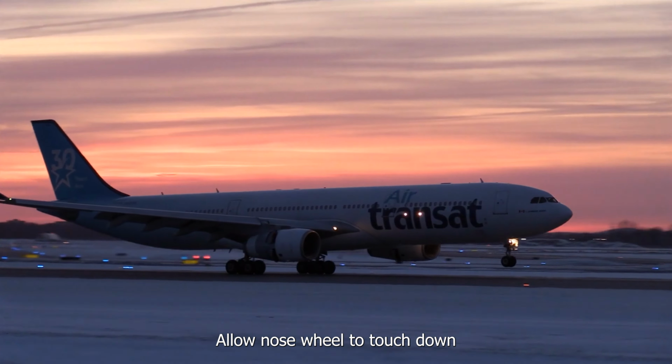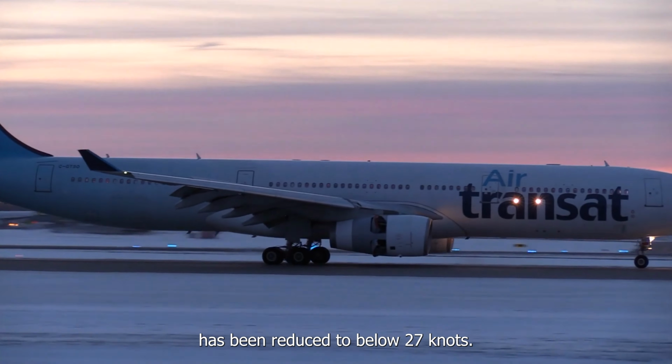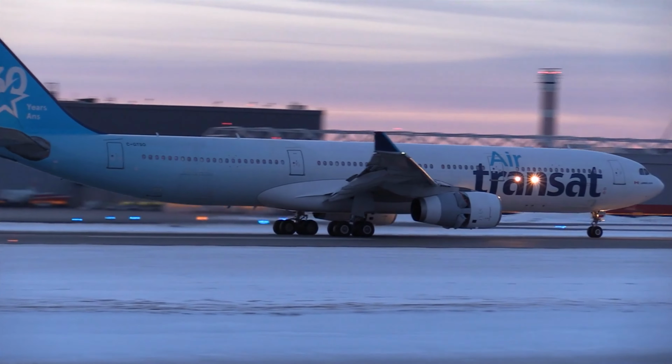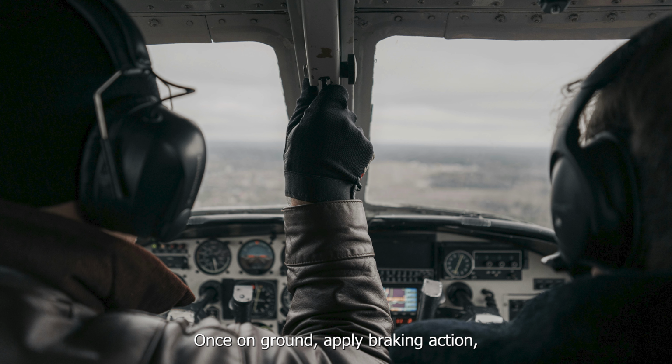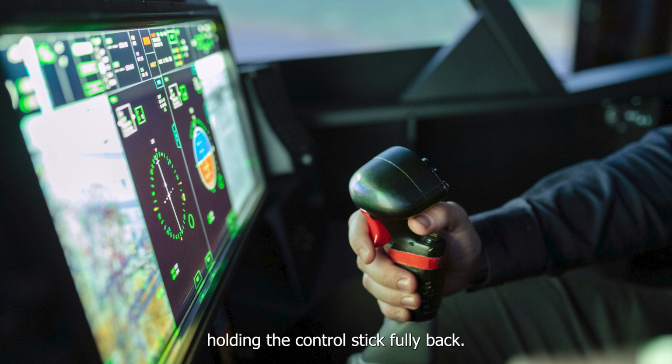Allow nose wheel to touch down only after speed has been reduced to below 27 knots. Maintain rudder pedals central when lowering nose wheel to ground. Once on ground, apply braking action, holding the control stick fully back. Steer the aircraft using rudder pedals only.